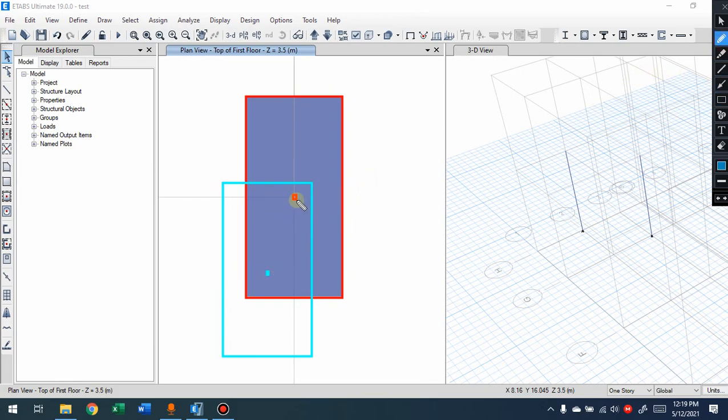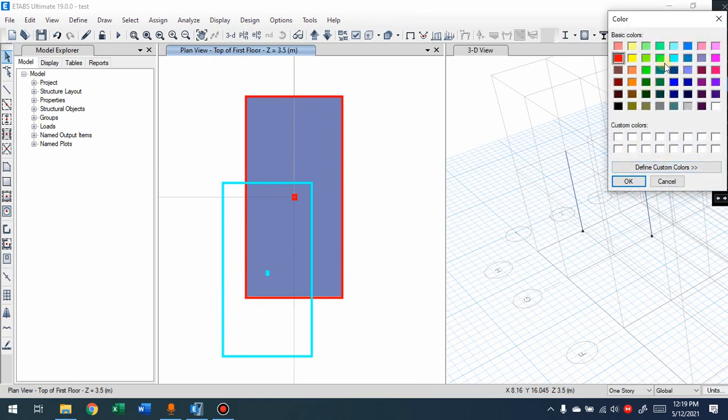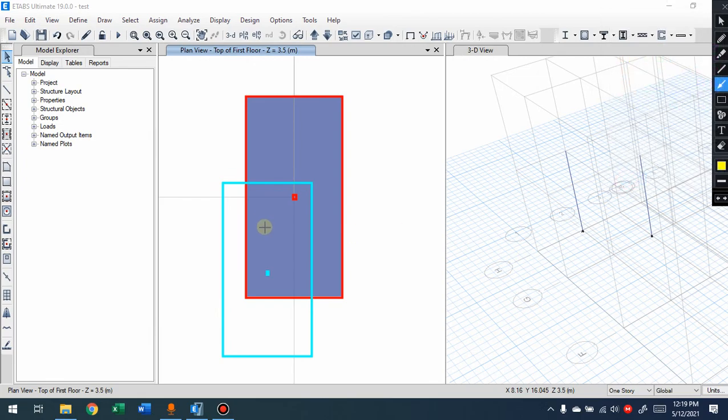Now this is a movement. You have a two-directional movement, where you move the column from two directions. One is from this direction and the second one from this direction. So basically you're moving the center of the column in two directions. Now that's why we need to connect with the link later, because when we're drawing the beam, we'll use this center, for example. Maybe even the beams we're going to move, doesn't matter, but the center of the column will come here. So that's why we're going to use that center later to link to the beam's center point.